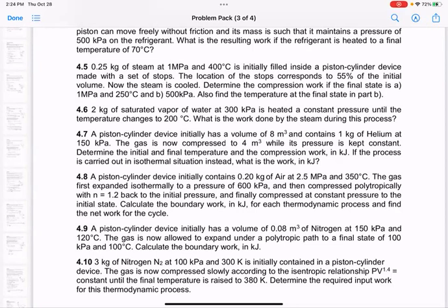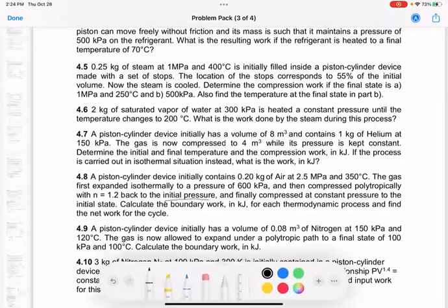And then, using the polytropic relation, knowing that PV^n equals PV^n, we can find the next volume, because the pressure at the end of the polytropic process is the initial pressure. So we sort of have three states here. We're going from 1 to 2 to 3, but really, because it's a cycle, we're always going back to the initial state. State 3 is really equal to state 1.